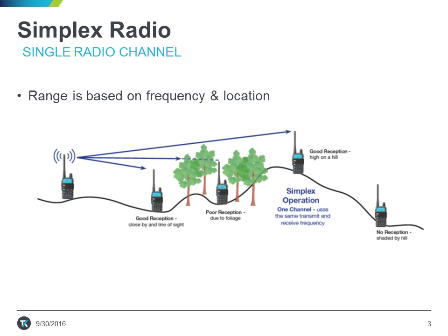This slide shows us simplex radio, basically a small system where we transmit and receive on the same frequency. In this slide, it's easy to see that the radio horizon for each of these mobiles changes. Those mobiles that are higher can see further distances, while those mobiles that are not as high can be blocked and their communication will not be heard by other mobiles.